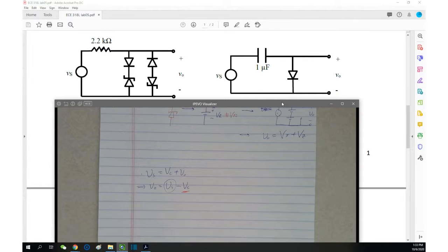Kevin is saying Vs minus Vg. This is the result of the circuit analysis, I think. However, be very careful. The Vs is sinusoidal. If you take Vs sinusoidal minus a constant, the result is still time-varying sinusoidal.